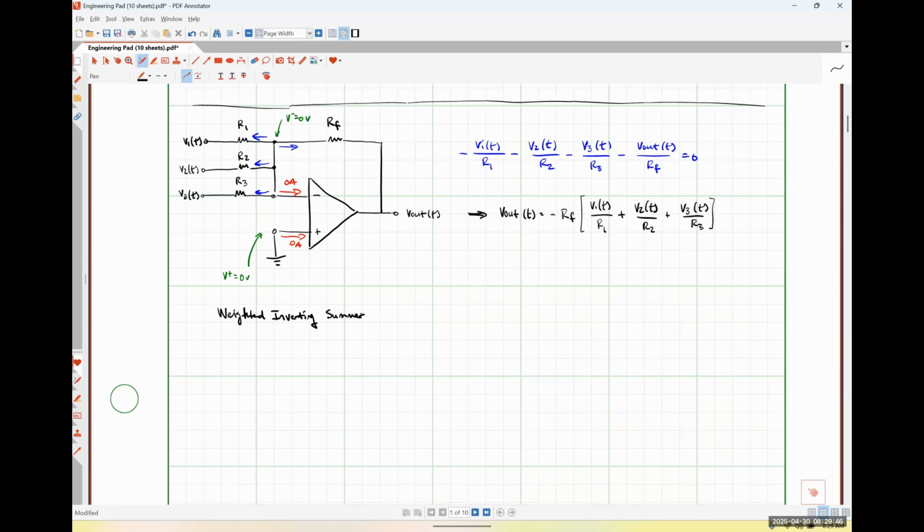So this is the more common way to perform the operation of addition using an op amp. And then we would run the output of this amplifier into another inverting stage to correct it to be a positive quantity, because it's actually easier to design that system than it would be to design a system that can handle multiple input signals and keep everything positive the whole time.